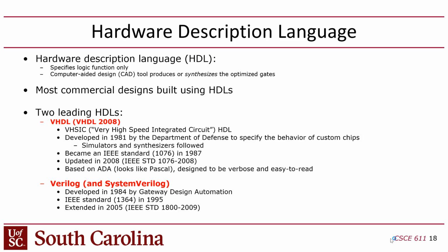And then Quartus is from Intel. It was originally from the FPGA company Altera, and then Intel bought Altera. So now it's from Intel. And it's the synthesizer. It's what takes your Verilog and converts it into a form, ultimately, that you can program the FPGA with. And then the circuit that you design snaps into reality. It becomes realized as a fully working circuit, much the same way you did in 211 when you put those chips on the breadboard and wired them up, and suddenly you had a working circuit, right? It's kind of like that.